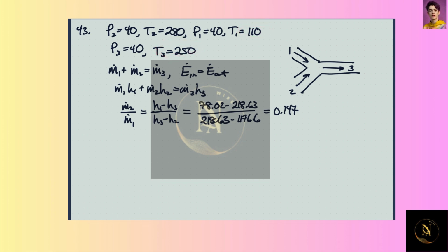And it's just because steam has so much more energy in it, basically because the enthalpy of vaporization for water is very high. I'm assuming this is superheated vapor. I didn't look it up, it might be two-phase, but you basically wind up boiling a lot of this water by mixing it with all this steam.